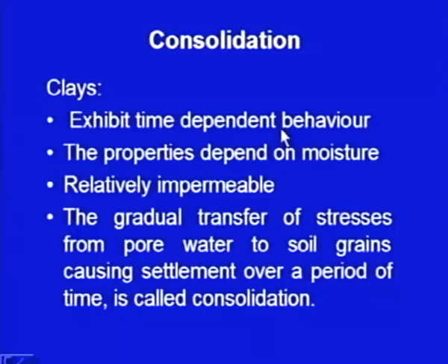What we mean by this is that if you construct a building on a clay soil and if you construct a building on a sandy soil, the settlements in case of the clay soils will be time dependent. They will be increasing with time, whereas in case of the sandy soils it occurs almost within the time in which the building is constructed.